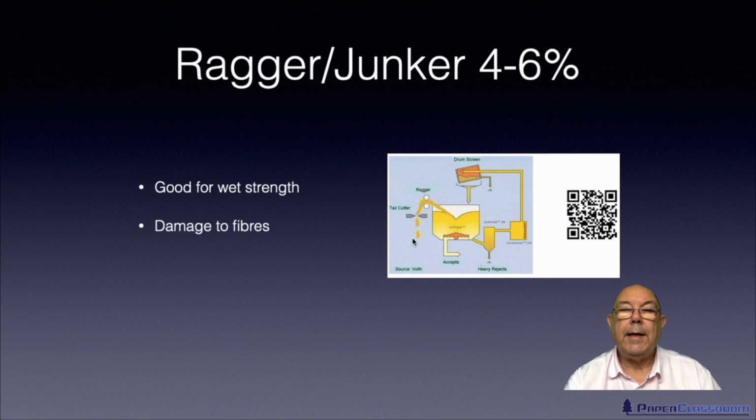And what that does is, if you've any flexible packaging there, like say magazines wrapped in plastic covers, then when the magazine hits that rotor, the plastic cover gets torn open, the magazine gets pulled out and shredded, and if you're not careful, that cover will also get shredded, and then you've got to deal with tiny bits of polypropylene or polyethylene, plasticky things all the way through your system. But by having those wires there that entangle things, it will take that wrapper out of the system before it gets a chance to be shredded.